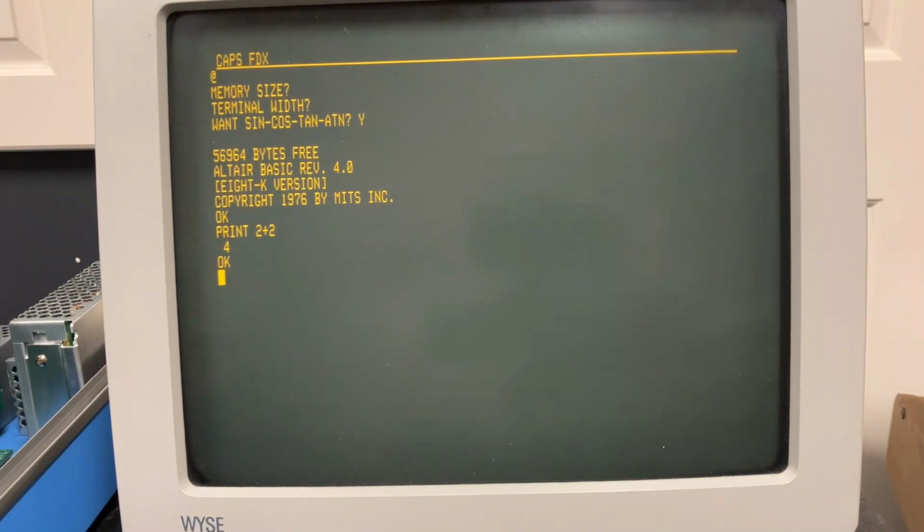If you want 1, the jumper should be towards the top of the board. If you want 0, it should be towards the bottom of the board. In the manual that I found for this board, it actually has one set of jumpers one way, the other set of jumpers the other way.